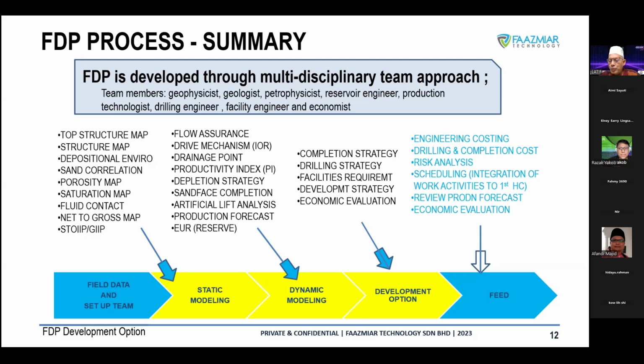We will outline the type of development option in terms of how many platforms there are going to be, and what the pipeline requirement is: is it going to be one water pipeline, one gas pipeline, one oil pipeline, and so on. So all those kinds of strategy will be more or less supported by front end, and the data will be based on the development option.